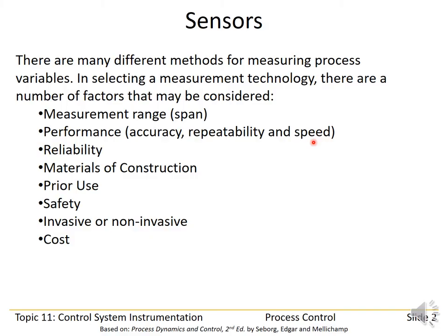If the measurement can be made quickly, control performance will improve. If the controller has to wait several minutes or more, if there's a lag of several minutes or more for the measurement, that will result in decreased performance of the controller.